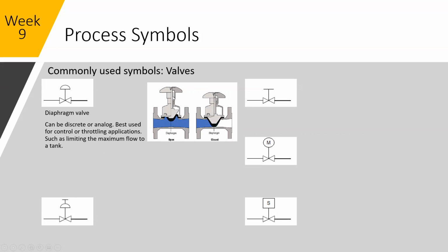As the actuator pushes this piece, it pushes the diaphragm through the throat of the valve, and the further down it goes, the more it would throttle down the flow. I see these used a lot for water flow applications, when sometimes you just can't slow a pump down enough.